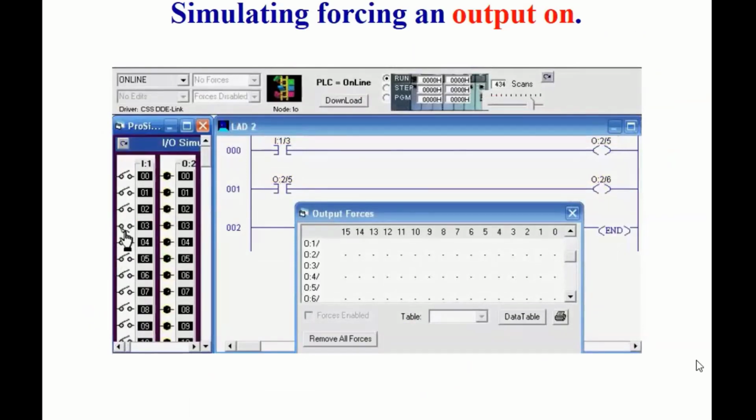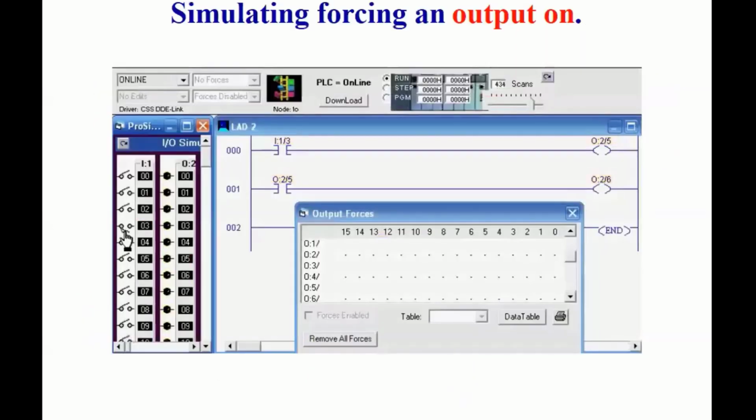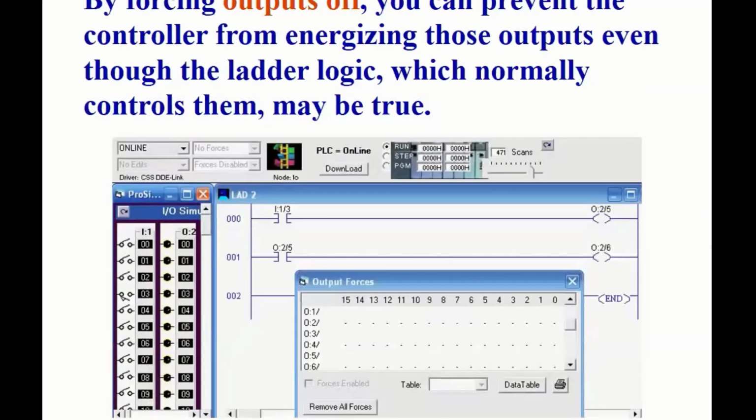Here's how you force the output on. Similar to the input force on. There we go. Forcing the output on. It is the same idea, right? You're going to step into the table and force that instruction to do whatever you want.